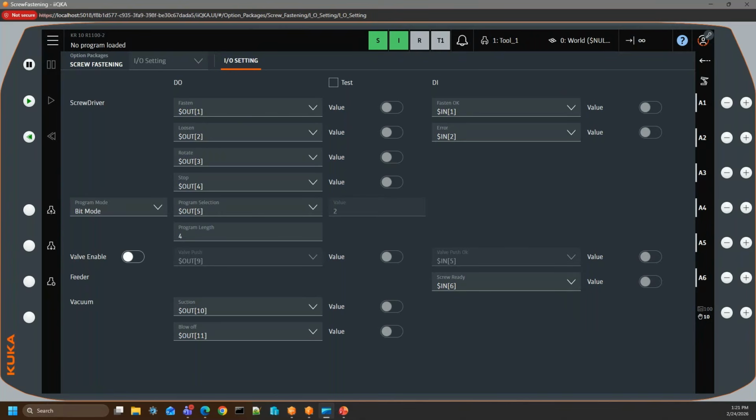How does the system detect or correct fastening errors? So the system is configured with functions to do the fastening and picking of the screws. There are error handling routines built into those functions that will automatically be invoked when the error signal is received from the screwdriver controller.